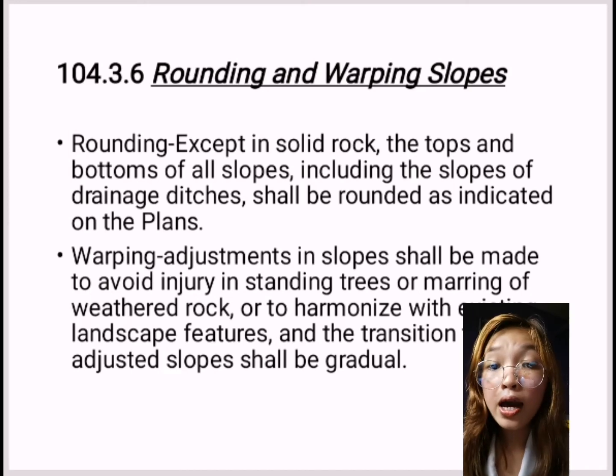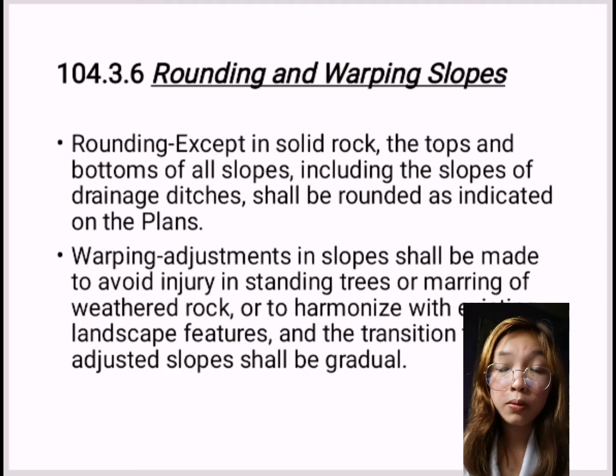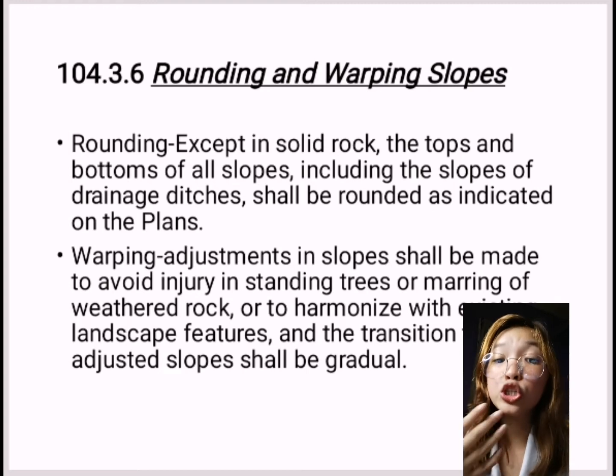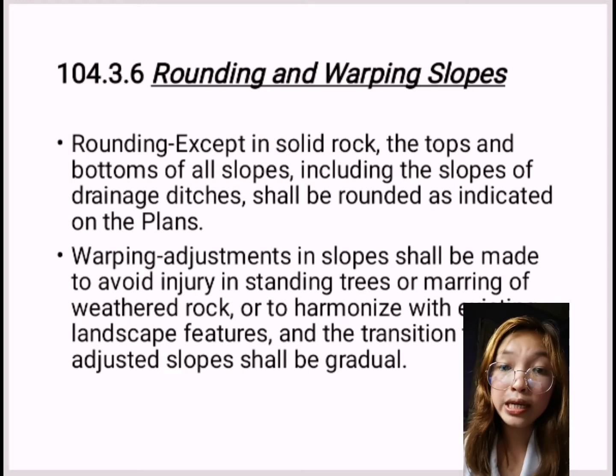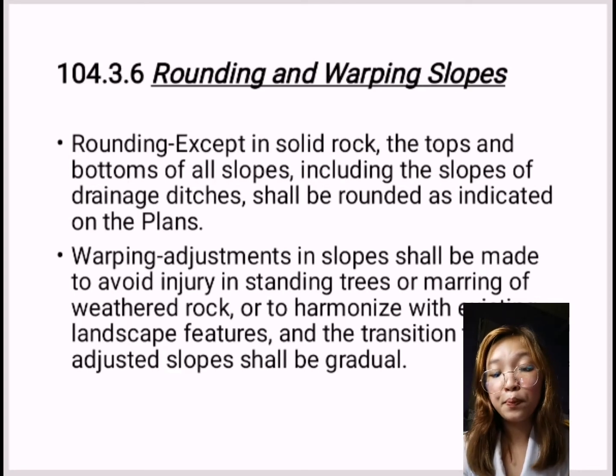So, at intersections of cuts and fills, slopes shall be adjusted and warped to flow into each other or into the natural ground surfaces without noticeable break.